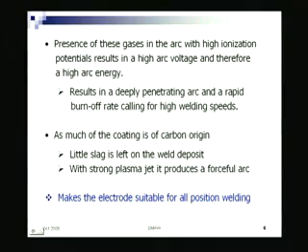At the same time, with a thinner layer of slag coating, the annealing effect will be somewhat less. So, on one side you have an advantage, on the other side you may have a little disadvantage. It is not a pure disadvantage, because you may not need that level of annealing; whatever shielding it is giving from heat dissipation is good enough. But the idea is to know that little slag is left on the weld deposit. Why? Basically, it gets burnt out and forms carbon monoxide.